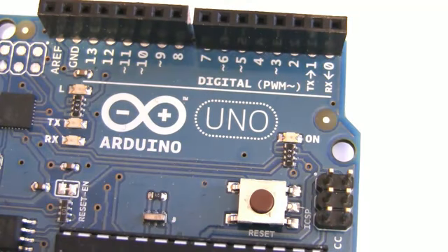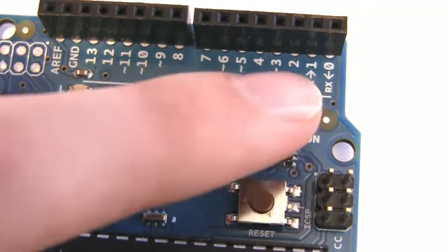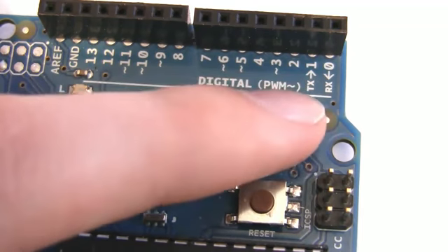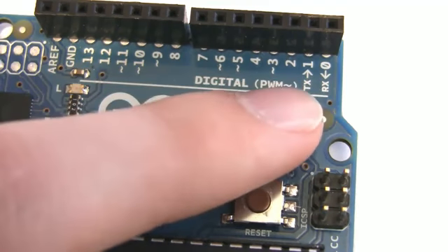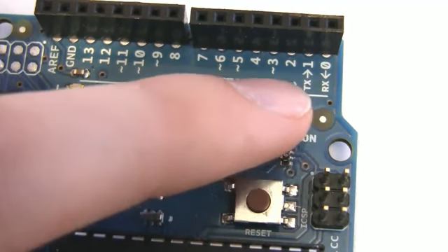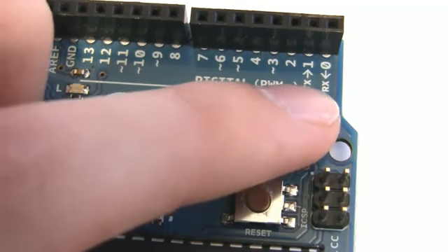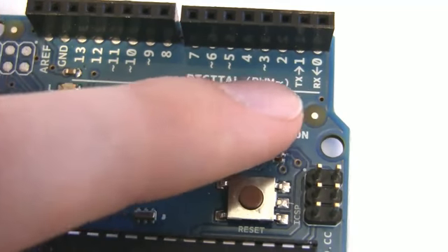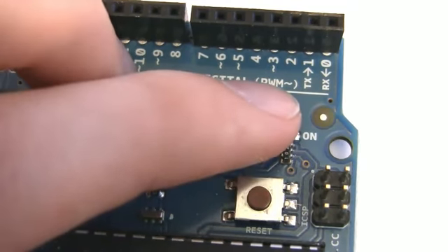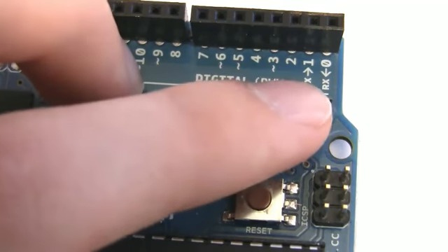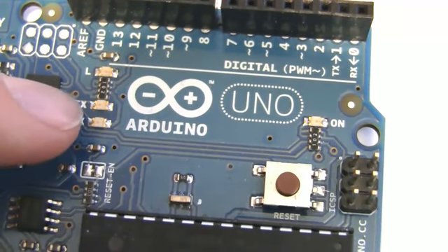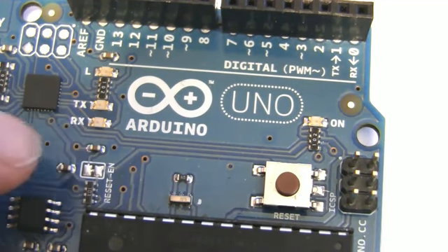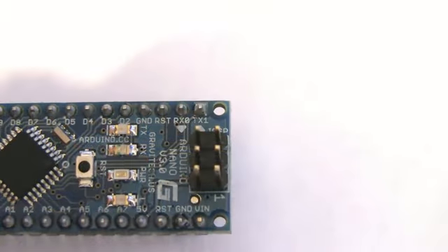Before we actually start communicating with the computer, let's talk a little bit about how we do this with the Arduino. If you look at the Uno, you'll see that there's a TX and RX pin on digital pins 0 and 1. Now you can use digital pins 0 and 1 while you're running your program for input and output. But during programming, these pins are multiplexed to be used as the programming pins for the Arduino. The RX pin is the receive, the TX pin is the transmit. When we call serial functions in the Arduino programming language, we're using these pins to talk back and forth between the computer and the Arduino. When you do this, you'll notice that the TX and RX LEDs will flash to indicate that you're sending or receiving data. The same story holds true for the Nano.